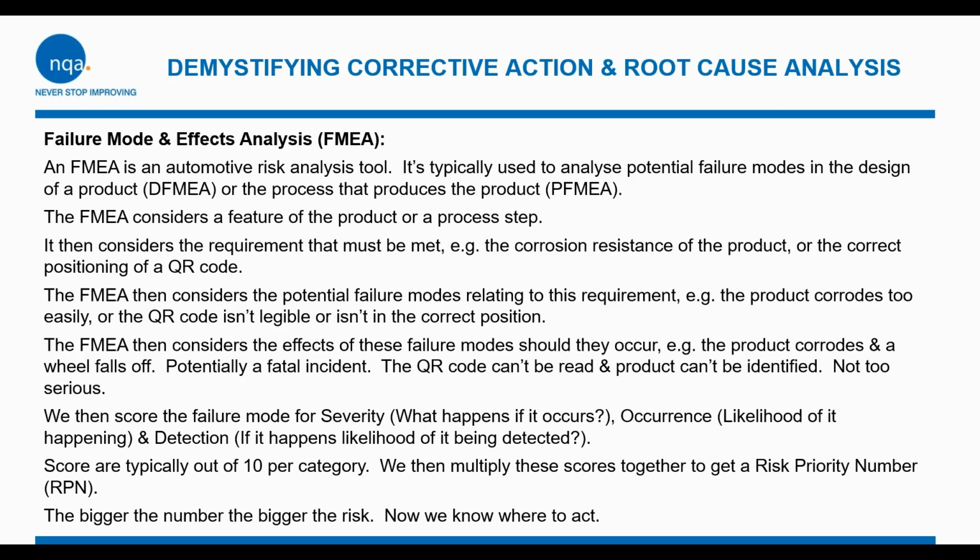The FMEA then considers the effects of these failures should they occur. The product corrodes and a wheel falls off. So potentially that's a fatality, or the QR code can't be read and the product can't be identified, which is not too serious, it's more of an inconvenience.